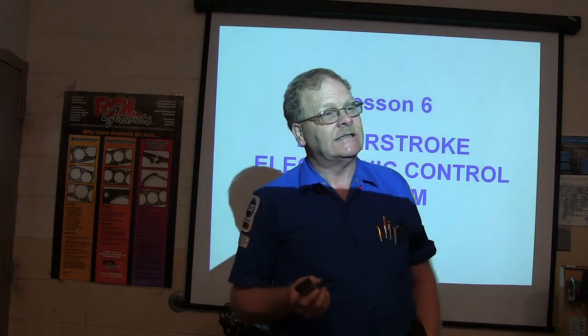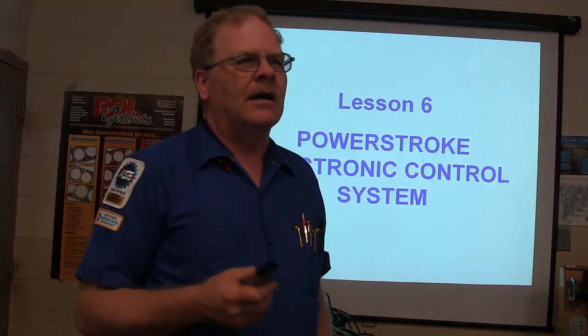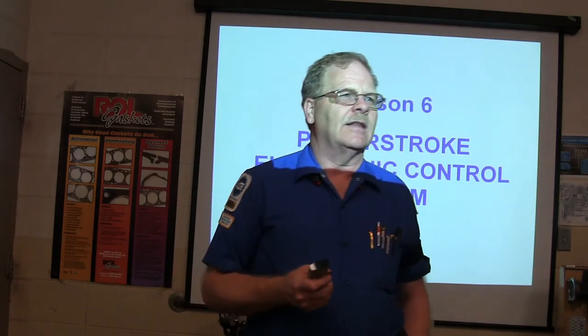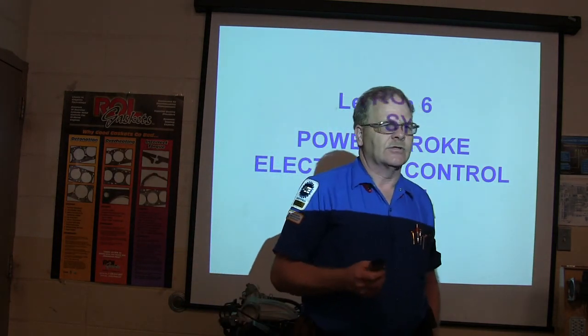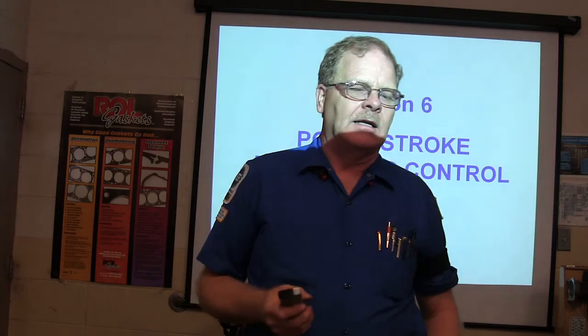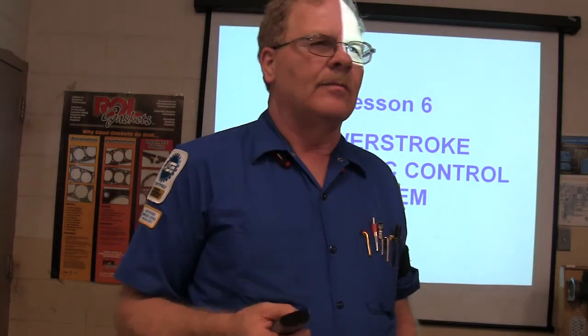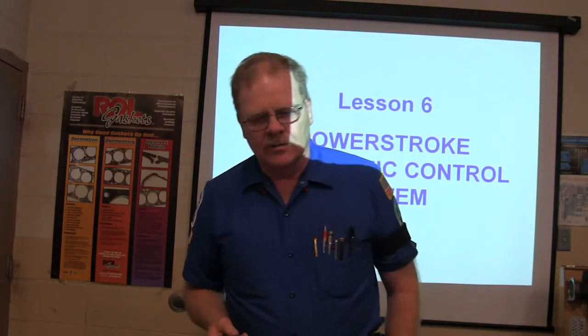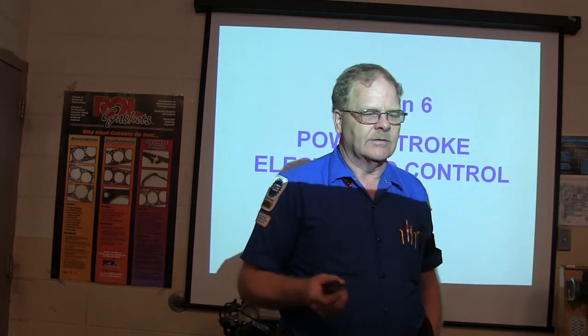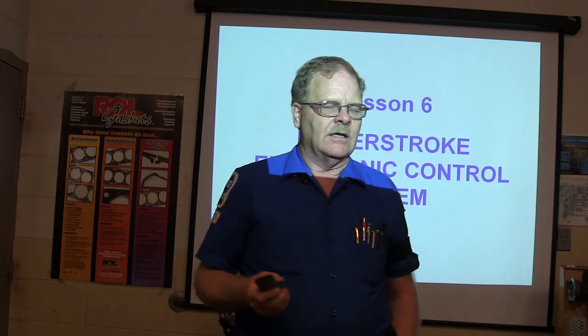We talked about diesel engines, right? We talked about how they fire on compression. We talked about how they need glow plugs because when you're squeezing the air, making it hot in a cold engine, the heat from the squeezed air goes into the metal, and you have to have the glow plugs to overcome that, and so on and so forth.